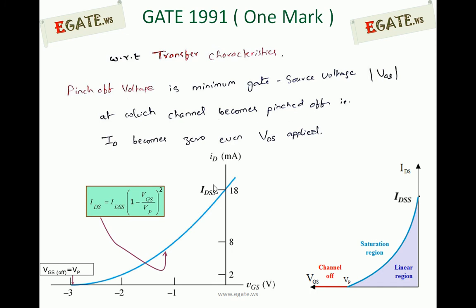If you apply positive voltage, the gate source junction becomes forward biased. By that time the important thing of high input impedance cannot be achieved. So the VGS value for N channel is always negative. As you apply more and more negative VGS, minus 1, minus 2, minus 3, the drain current gets smaller, because the depletion layer becomes larger and the effective channel length gets reduced.